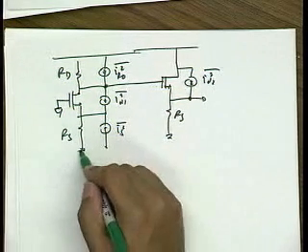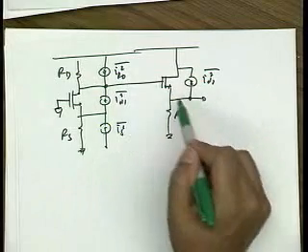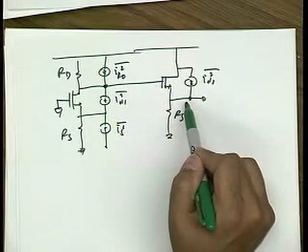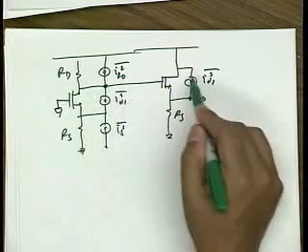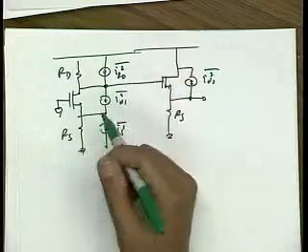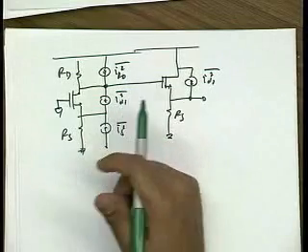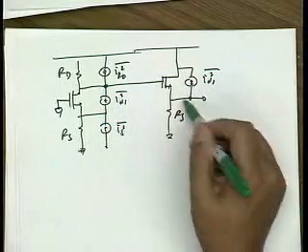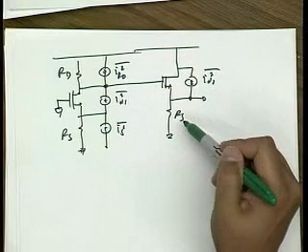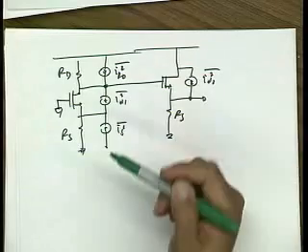The very simplistic way to look at it is that the noise sources here, basically, the gain here is very low, right? The voltage gain. So if I look at the voltage noise here to the output, it's already gone through some gain through this transistor, whereas the output noise here has no gain. So if you think about it in terms of cascade, it's not really a cascade, it's very crude. The noise figure of the first stage is going to dominate the overall noise. And I know the noise of the second stage is not that large, partly because of this degeneration, right? In fact, I know that this noise will contribute to the output by a factor of 1/4, because the gm of this transistor is equal to this RS. So I get a 1/4 factor.